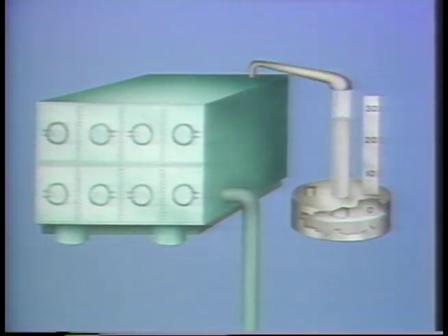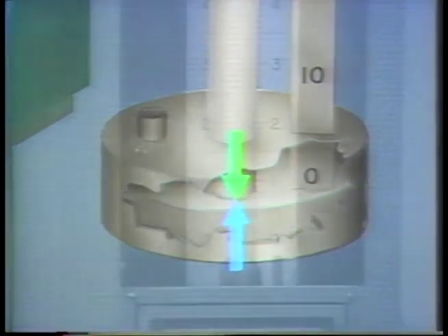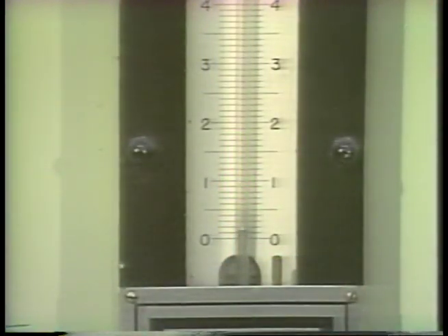When the condenser is shut down and at atmospheric pressure, the pressure on both ends of the tube is the same. Since the pressure is balanced, no mercury is pushed into the tube, and the mercury level is 0. Now, as the vacuum pumps are started and pressure in the condenser decreases, the mercury begins to rise up the tube. In other words, the mercury begins to flow from the higher pressure in the atmosphere toward the lower pressure in the condenser.